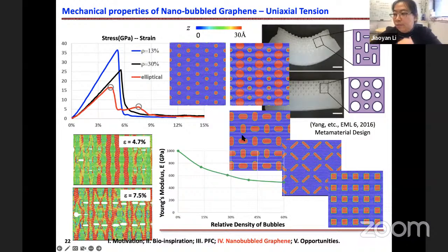So assembled inversely, like across with each other. The red line shows some kind of abnormal double peak stress-strain curve. That is because of the crack tip trapping by the vertical and the horizontal elliptical bubble. So after the first stage of damage propagation, the trapping mechanism plays a role and the material can afford further loading. That's why you can see the second peak over there.